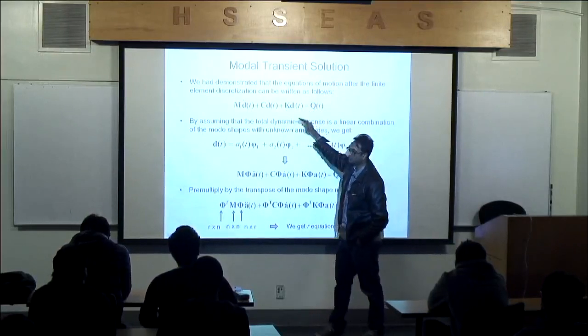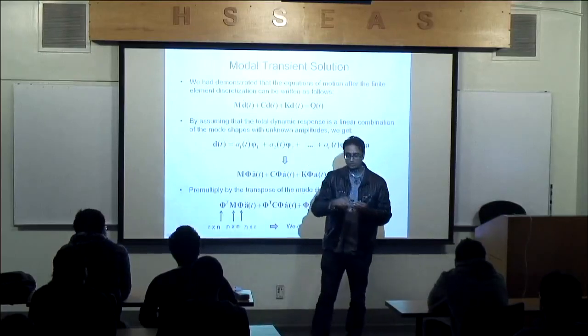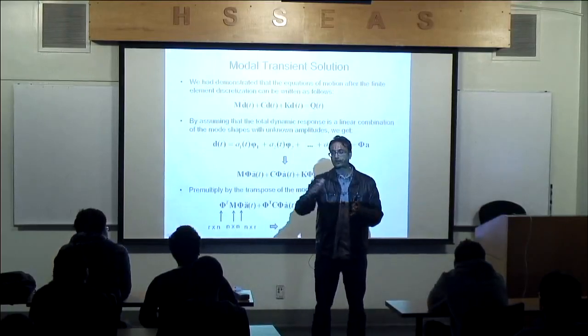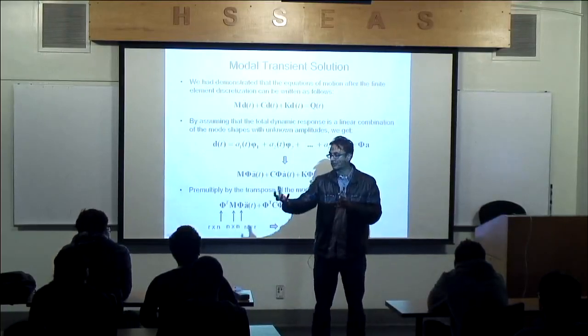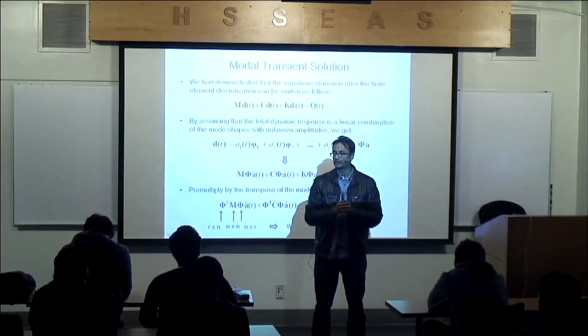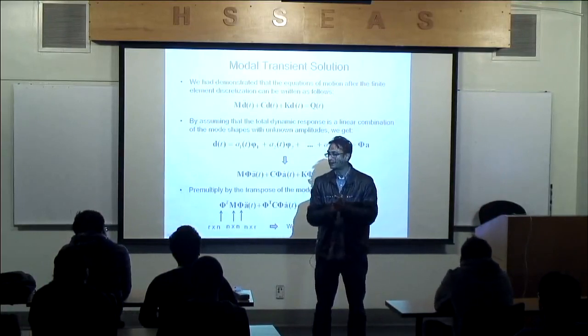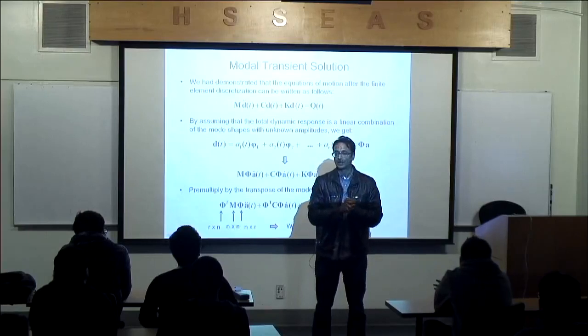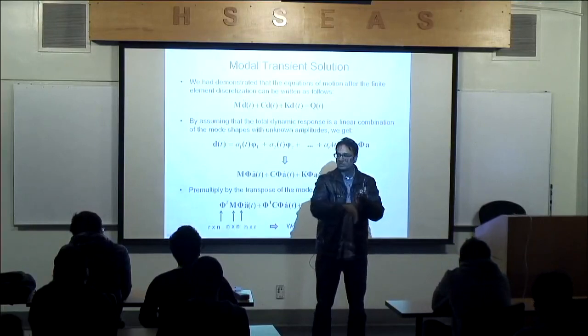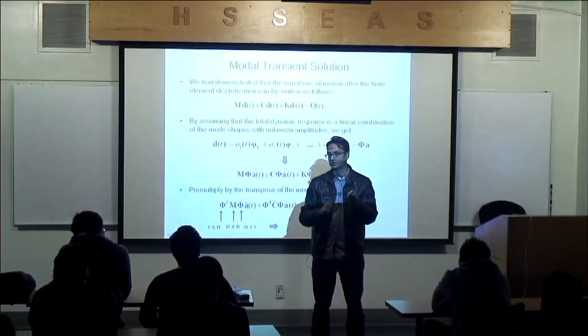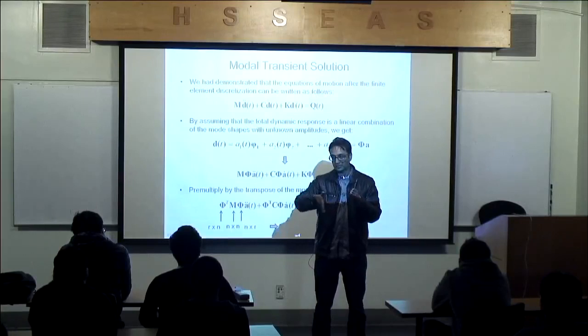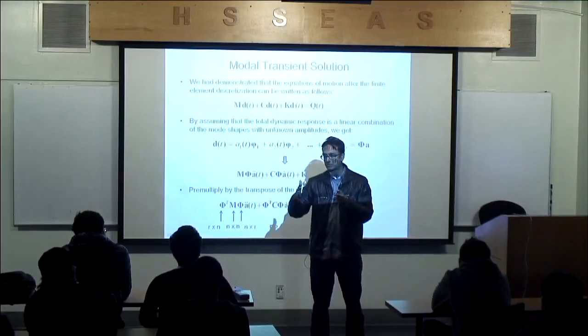Let's say now that for the problem of interest, I'm interested in stuff up to 50 hertz, 75 hertz. For whatever reason, that's what I think I should be using because my forcing functions may not have frequency content beyond them. Maybe in that problem I'll get 10 modes up to 50 hertz, right? 10 frequencies, right?